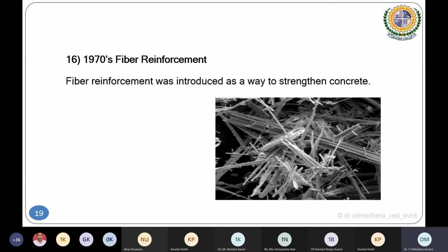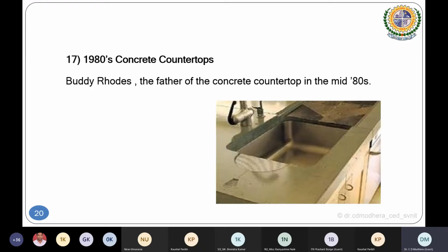In that case, we are supposed to use discrete fiber made of steel, glass or any material prevailing. If discrete steel fiber is used, it can work as good as continuous fiber, only for certain depth and width, and that is derived based on the aspect ratio lambda, that is, development length L by D ratio. The aspect ratio is L by D, if it is circular in nature. Fiber reinforced concrete nowadays has many types: acrylic fiber, GFRP, discrete steel fiber. GFRP is different, it is in sheet form, which we'll also discuss.